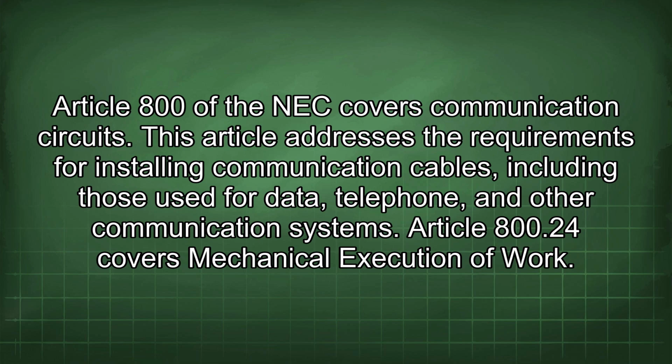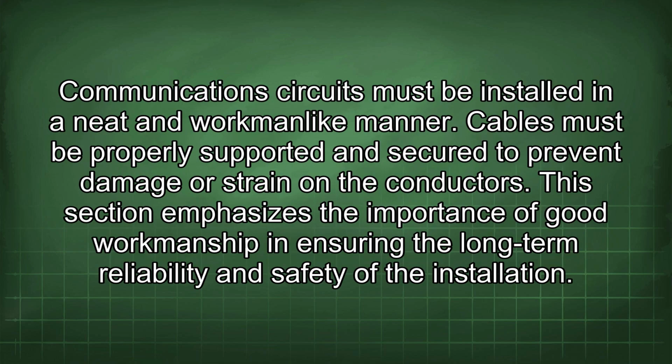Article 800.24 covers mechanical execution of work. Communication circuits must be installed in a neat and workmanlike manner. Cables must be properly supported and secured to prevent damage or strain on the conductors. This section emphasizes the importance of good workmanship in ensuring the long-term reliability and safety of the installation.